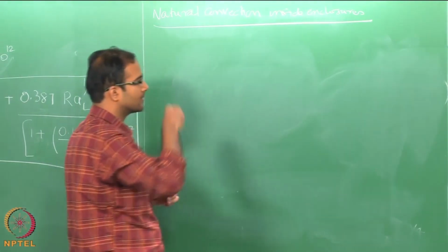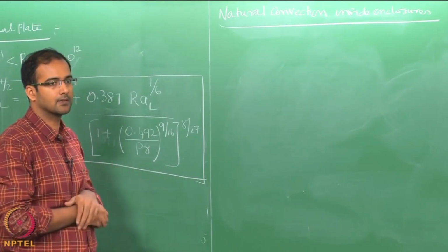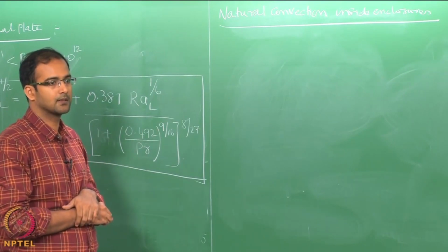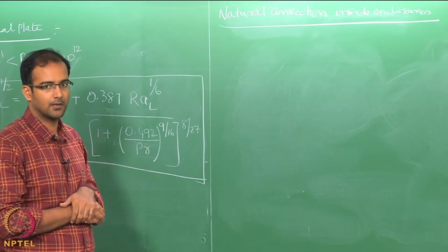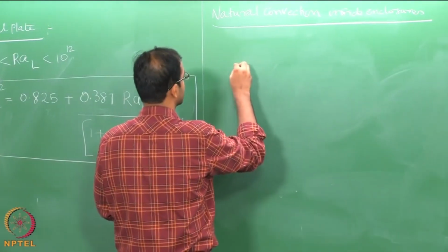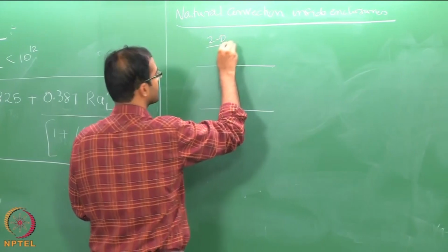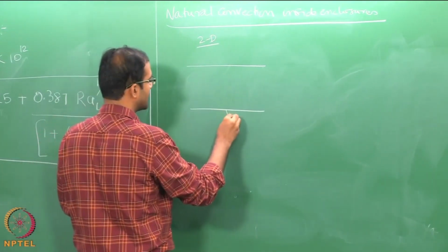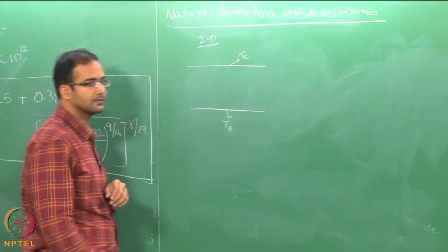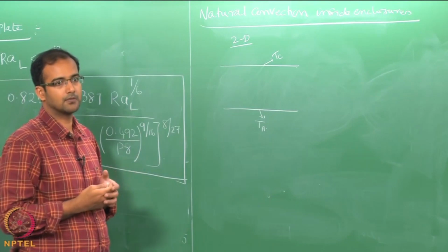and in fact these are far more interesting than the external natural convection, because external natural convection we are doing in detail because of the availability of solutions, but the more interesting phenomena occur when you have natural convection in cavities. So, one of them is that you can have two parallel plates in 2D configuration. Okay. You can, for example, heat the bottom plate and keep the top plate cold. Okay. And what happens now, again due to the buoyancy forces.